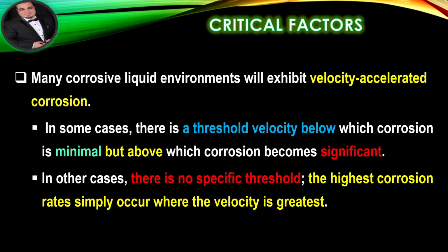Many corrosive liquid environments will exhibit velocity-accelerated corrosion. In some cases, there is a threshold velocity below which corrosion is minimal but above which corrosion becomes significant. In other cases, there is no specific threshold. The highest corrosion rates simply occur where the velocity is greatest.